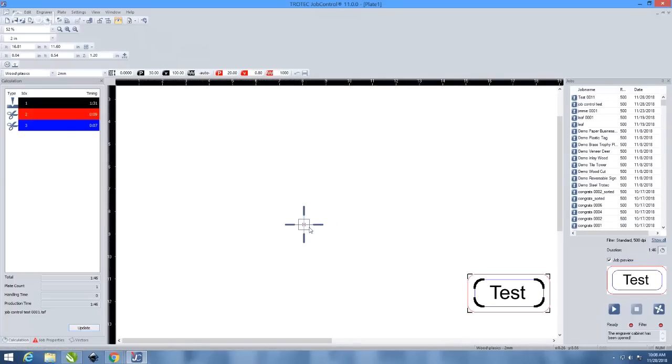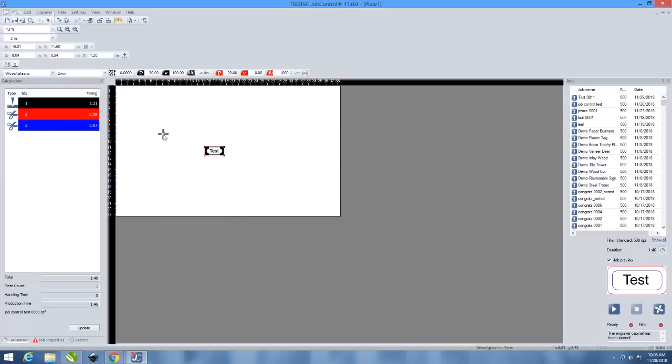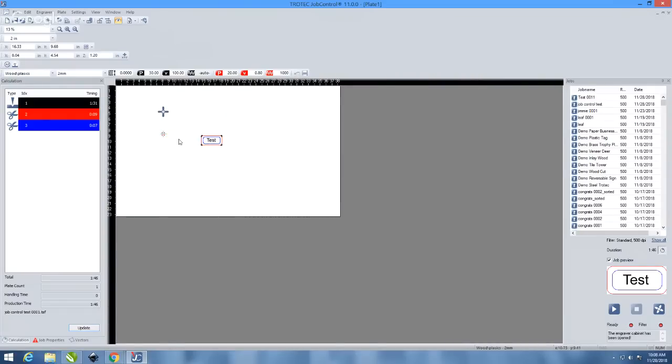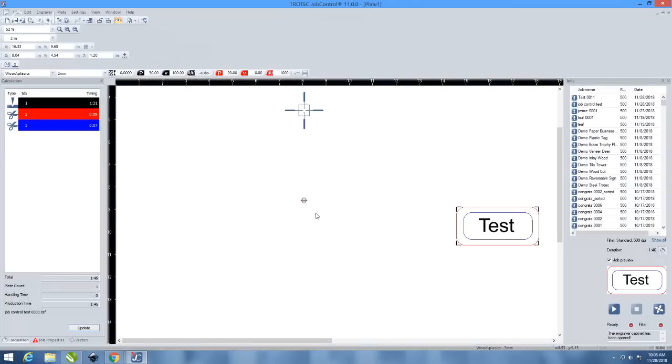You can now see it has added this little dot here. So if I move the laser head out of the way, we have a dot, marker, sorry. And now that marker can be used to position a job. And the great thing about them is you can place as many as you'd like. So if you're maybe doing jobs on different materials and you want them to be cut in a specific orientation, this may be how you do that. Again, there's a million ways to do anything, but we think that the markers here are very useful. And again, like I said, you can always add more.